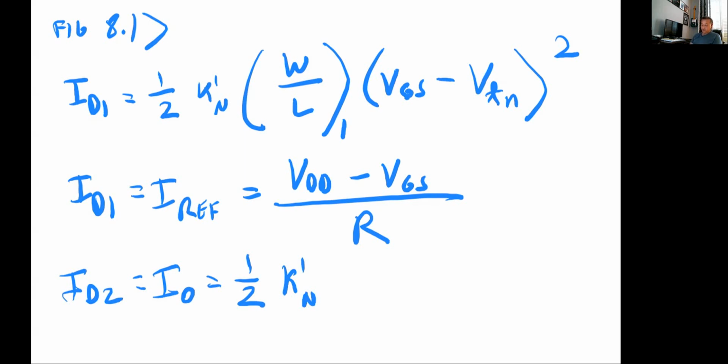That's why we distinguish K prime from K, because K is K prime times the ratio. But we can adjust essentially the W's, and that's what we're trying to come up with. Ideally, you want design equations that are in terms of the ratios of W's of different transistors. That's really a good design, the best type of optimal design philosophy.